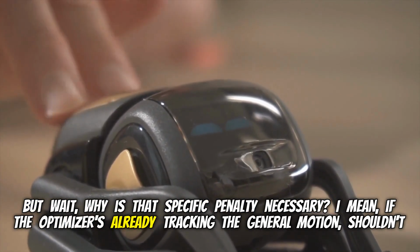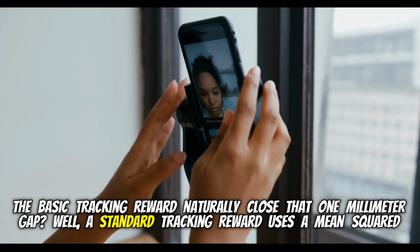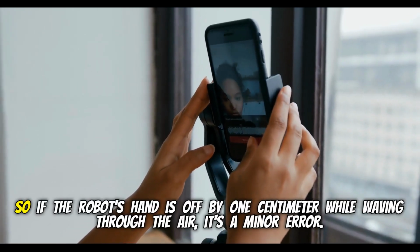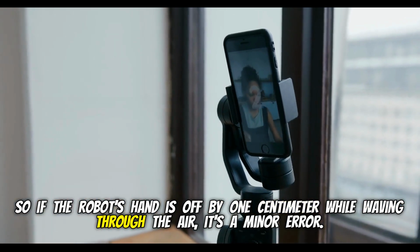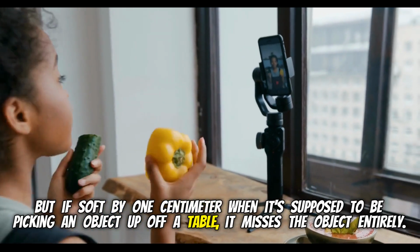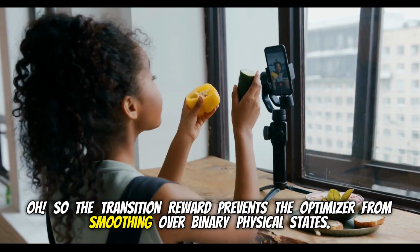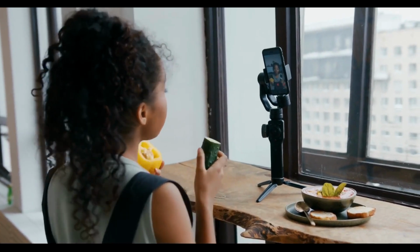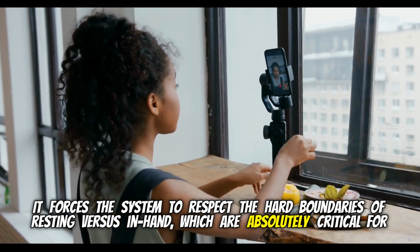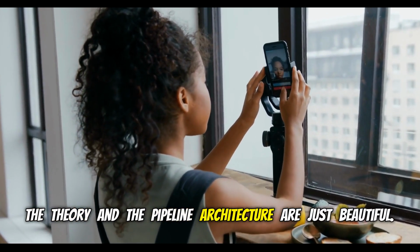I mean, if the optimizer is already tracking the general motion, shouldn't the basic tracking reward naturally close that 1 millimeter gap? Well, a standard tracking reward uses a mean squared error loss function, which naturally smooths out physical states. So if the robot's hand is off by 1 centimeter while waving through the air, it's a minor error. But if it's off by 1 centimeter when it's supposed to be picking an object up off a table, it misses the object entirely. Oh, so the transition reward prevents the optimizer from smoothing over binary physical states. Exactly. It forces the system to respect the hard boundaries of resting versus in hand, which are absolutely critical for successful multi-stage tasks. The theory and the pipeline architecture are just beautiful.